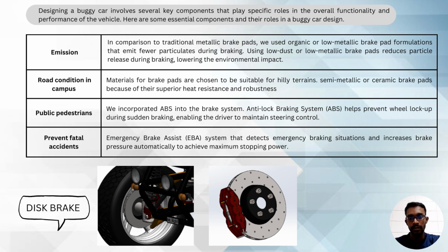Designing a buggy car involves several key components that play specific roles in the overall functionality and performance of the vehicle. Here are some essential components and their roles in buggy car design. First, we are going to look at the disc brake. There are four main things that we have to consider in designing. First is emission. So we are going to use low dust and low metallic brakes to reduce particle release during braking, lowering the environmental impact.